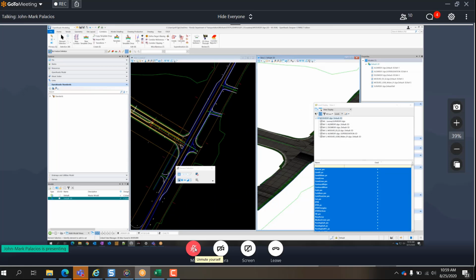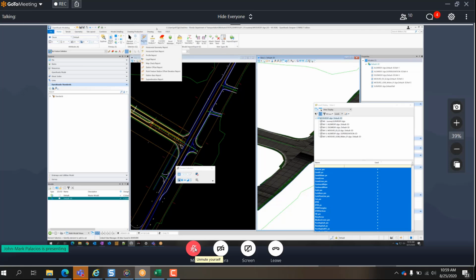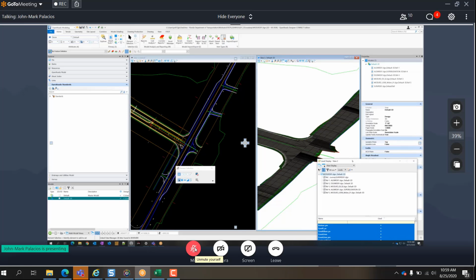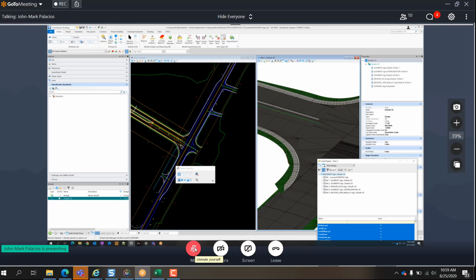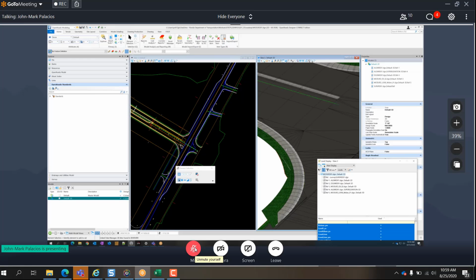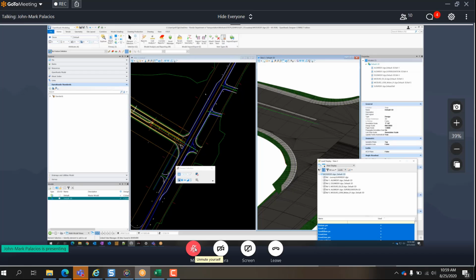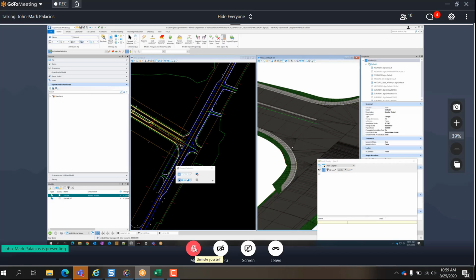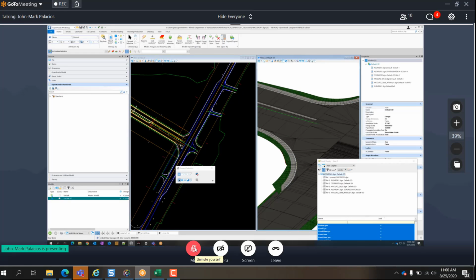So, Earthwork. Give me a second because we don't have a write-up on this. Basically, Earthwork is a different approach than now. What we have to do is a surface comparison. We have the existing ground right here, and we need a top surface to use as a comparison. There are a few different ways to create that top surface. I'll show you where the tools are here.